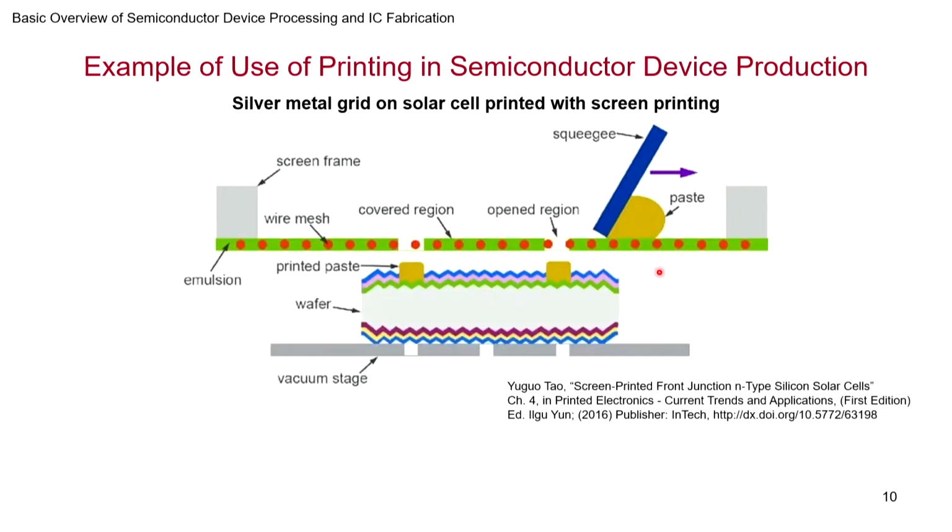But when they make the metal contacts, very often, since metals could be deposited at lower temperatures and you just need to have a small anneal following it, you actually often end up making metals by printing. Very often in many of the devices you will have silver at the top, silver patterns, okay, silver mesh that will be there at the top, that will be screen printed.